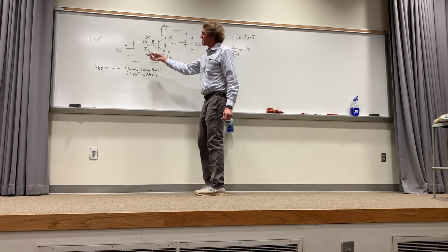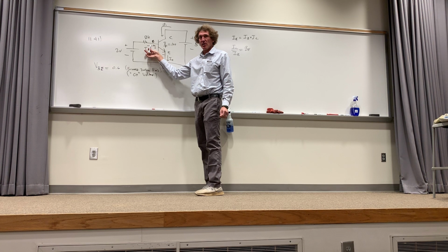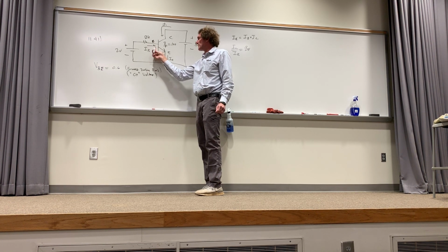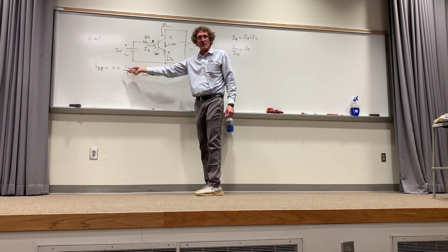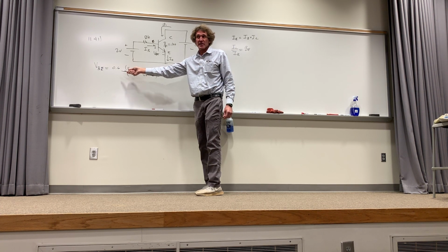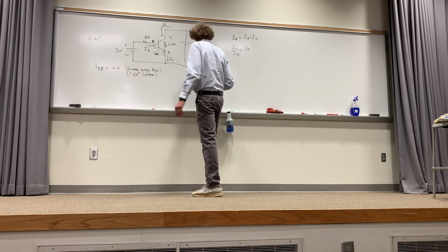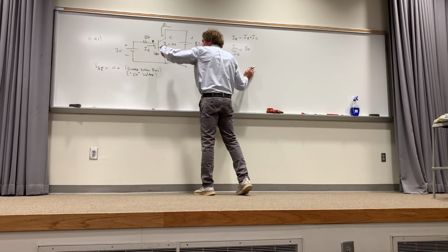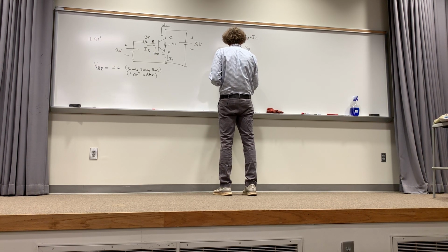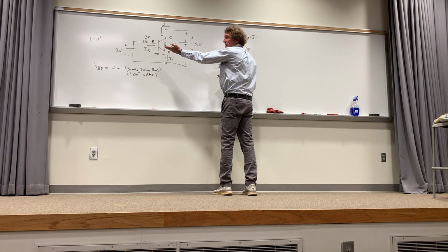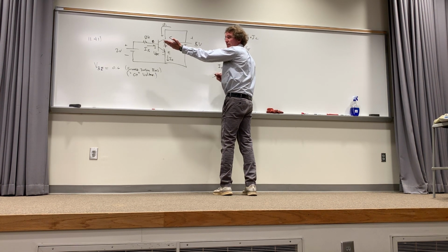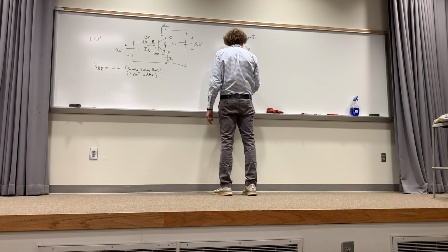well, the voltage here is 2 volts driving it, right? You all see that, class? Right? 2 volts. But there is a 0.6 of a volt drop here. That was given right there. Most of the time with transistors, and the ones you see on the final, it would be 0.7. That's what I'll give you. But here, for some reason, he's chosen 0.6, probably just to throw you a curveball. So now you have to say that the total voltage driving current this way would be 2 minus 0.6, and the thing that limits current is the 50K ohm resistor. You all see this, class? 50K, right? So I divide by 50K.